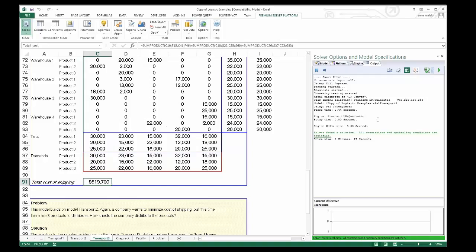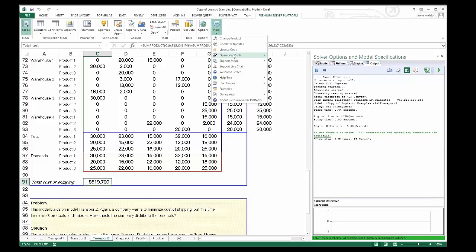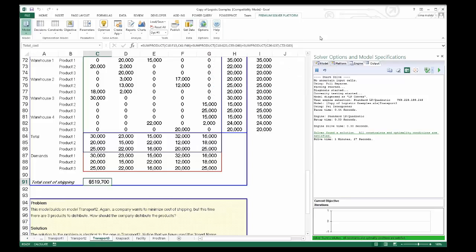Now, imagine you have used this guided mode for a while and you are solving over and over. You might want to get rid of the dialogues that you have to click through every time. To make this change, let me show you again. Click on Help, Operating Mode. You can see I've selected Guided Mode. There are two more options. Instead of going to Expert Mode, which eliminates the help, you have another choice, Auto Help Mode, that will only bring up the dialogues when there is a problem. But I'm going to keep the guided mode for our examples today.